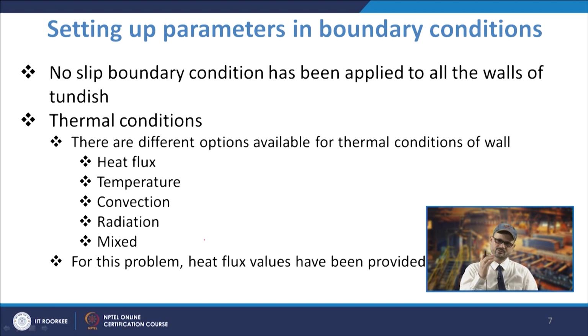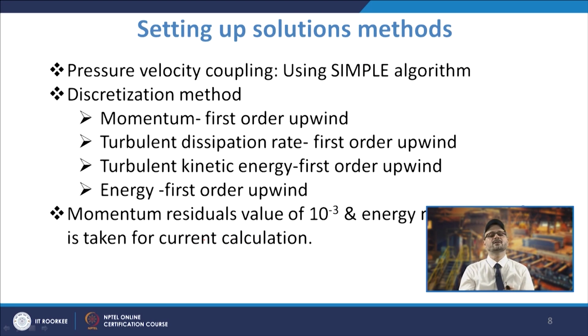Once the number of grids is more, the time requirement will be more. So these wall boundary conditions are to be provided with proper understanding of what kind of model you are taking, and how that will be helpful in capturing the flow which is occurring inside the domain. So that is about the wall boundary conditions.